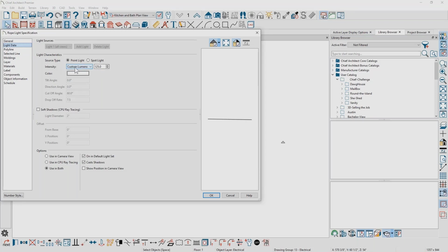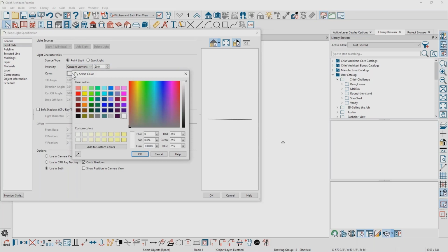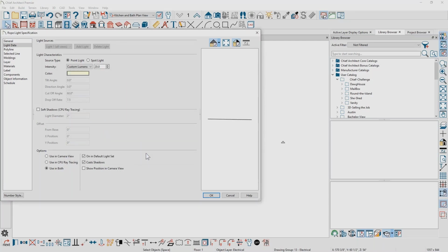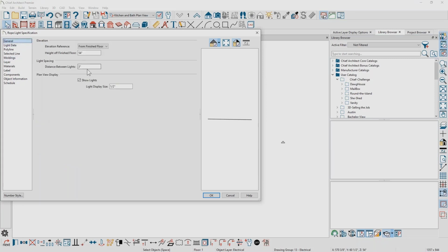The intensity of that light. Have you changed that when you're doing your lighting? Mm-hmm. Okay. So sometimes I might set that down to a lower number, and then you can also change the coloring of it. So depending on what you're after there, you can put a slight coloring on it. And I'll also probably reduce the number of lights that are associated with this thing so that there's not a ton of lights in here.